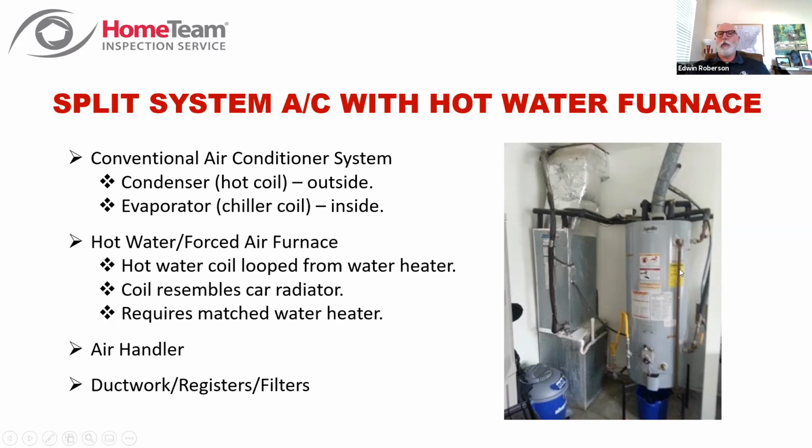What you've got inside this is a big coil sitting in this tank of water that is a closed loop that then cycles water through this loop. So your hot water heats this up. When the house needs heat, you open a valve, turn on a pump, and you're pumping water out of the top of the hot zone of this water heater and through this coil, blowing air across it, and then returning that water back to the water heater.